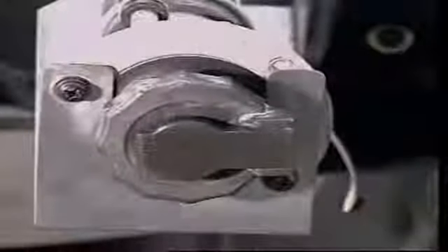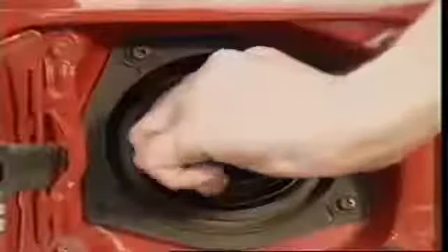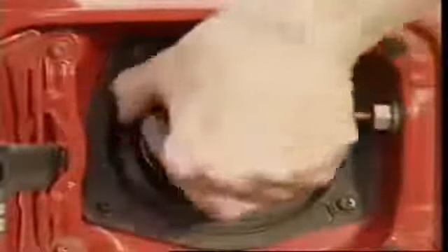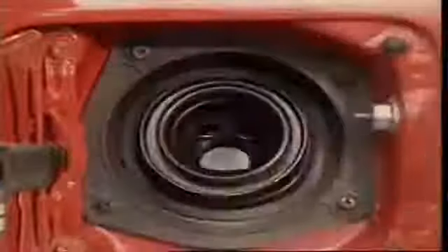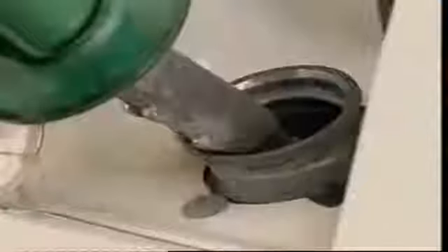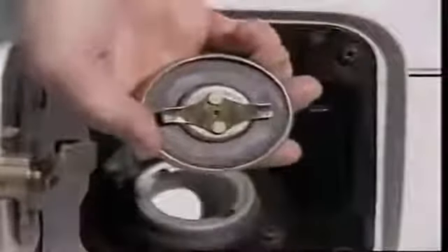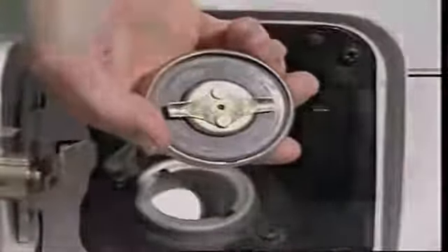The filler cap seals the filler neck to keep out water and foreign objects. Water can corrode internal passages of fuel pumps and carburetors. The cap on the petrol tank also stops petrol vapour escaping and polluting the atmosphere. This is important for petrol, which is very volatile and vaporizes easily, especially in warmer climates. Some petrol caps have a low pressure valve built in. It keeps a balance between the pressure in the tank and the outside atmospheric pressure.